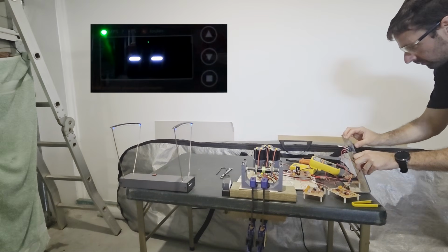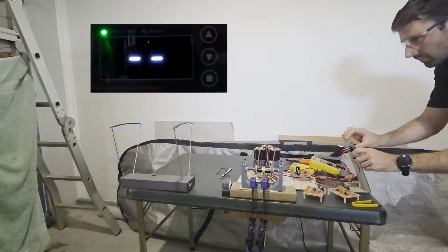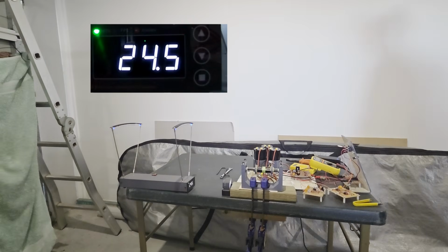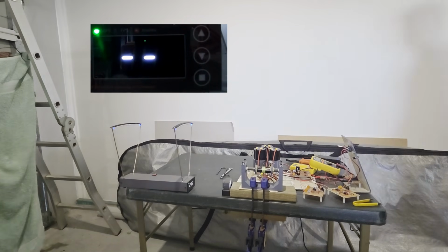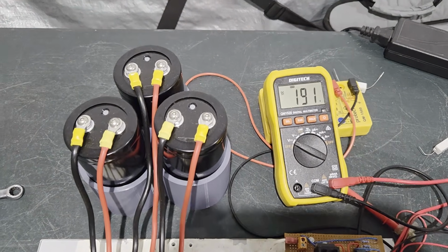With the additional layer on the coil, it decreased the velocity by 3.5% to 24.5 meters a second. But it did have a higher efficiency at 3.55% compared to the baseline's 3.16%, due to the less energy from the capacitor bank being used.